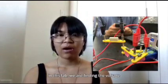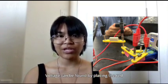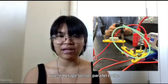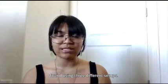In this lab, we are finding the voltage and current of different resistors. Voltage can be found by placing the red and black probe that are attached to the current voltage sensor parallel to the resistor. Current, however, will be found using 3 different setups.